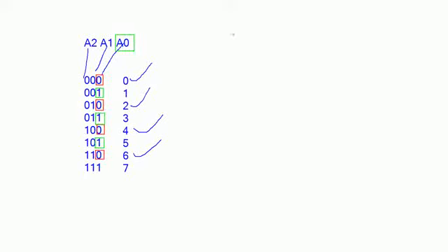Now, if you are taking a particular memory device, never think that this particular memory device is always giving the even addresses. It is not like that actually. This memory device gives the even as well as the odd addresses. It is a sequential number. But depending on the address line, which is the A0 bit position, we can differentiate. We can make one memory device an even memory, and we can make another an odd memory. That is decided with the help of the A0 only. Just remember that point. After that you will come to know how to assign the even addresses only and how to assign the odd addresses only.